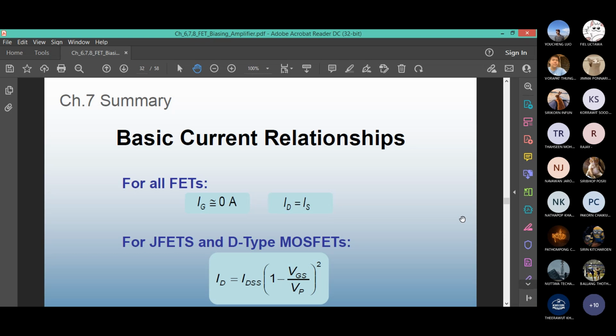The JFET is a high input impedance device, so on the input side you have a high impedance, the unit of which will be ohm. A high input impedance is often approximated as an open circuit, right? So when the circuit is open, the current really cannot flow, or whatever flows is so negligible, you can say IG approximately 0 ampere.